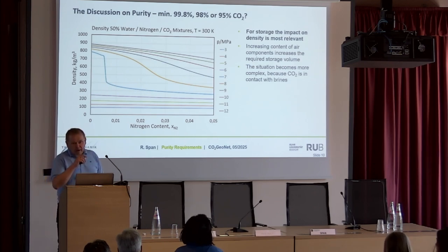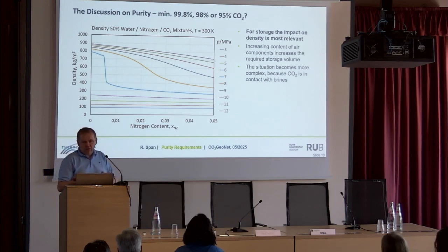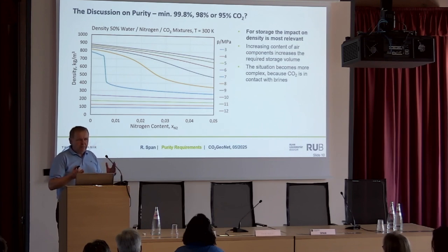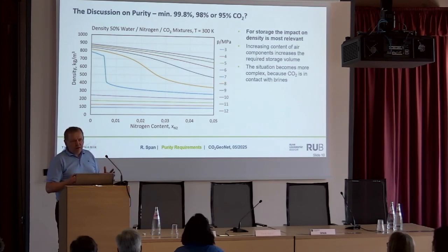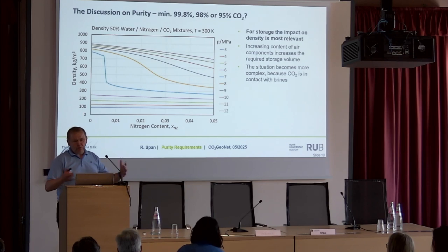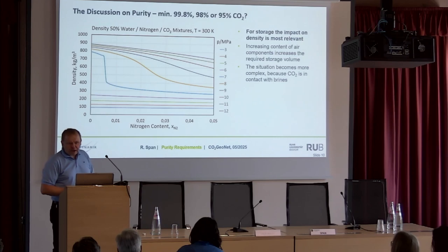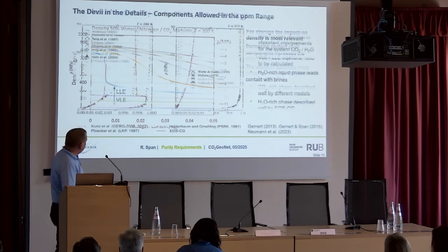Now, in most cases, when we talk about saline aquifers, of course, there will be water involved. So we do not have only the system CO2 nitrogen, we do have a system where water is involved, but that doesn't make a big difference because the nitrogen is anyway dissolved in the CO2 phase. And close to the injection site, you will have two separate phases, a water-rich phase and a CO2-rich phase. So, at least to my understanding, it doesn't make a big difference whether we have a dry or a water-rich system.